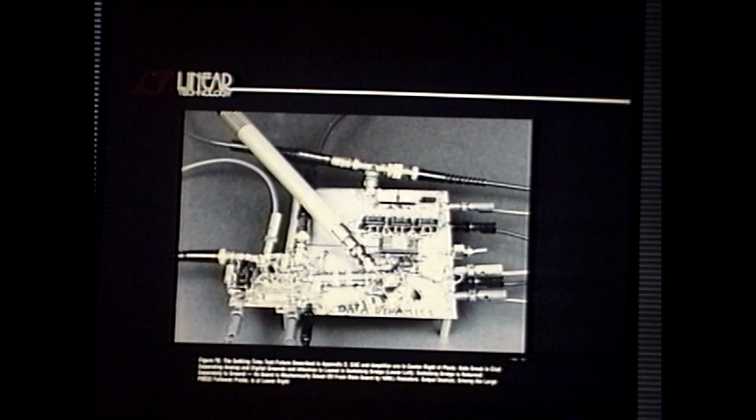In theory, when you tie analog and digital ground together, you should have almost no current flowing in that reference connection. If you do, something's wrong. Because that's what you're doing, you're referencing the supplies to 0. There should be no current flowing in that point. If there is, you've got a ground loop.